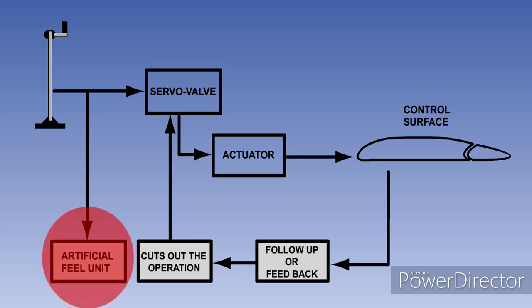When fully powered flying controls are operated, there is no aerodynamic stick force fed back to the pilot. He therefore has no feel for the aerodynamic effect his control movements are having, meaning that there is a danger of him over-controlling the aircraft or of overstressing the airframe. To prevent this problem, and to ensure that the controls centre when the pilot's control input is removed, artificial feel units are fitted in parallel with the powered flying control units, or PFCUs.